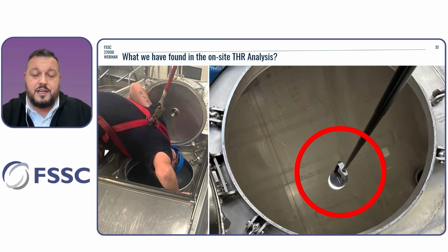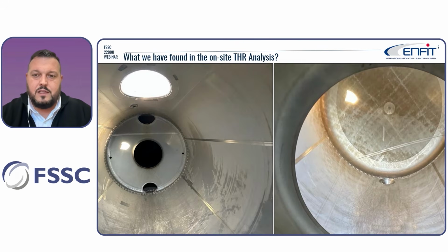Controls that are done after cleaning are mainly by the operator or the driver going inside and checking visually, which is not always so good. That's why we also invented a 360-degree camera, which is on your right side now, and you can see that when this camera goes inside, with just one click, we can take a photo. This is a photo from the 360-degree camera showing what cannot be seen just by looking when you go into the manhole with your own eye, because this shows that there are some scratches and some remains of the product that were not cleaned sufficiently.